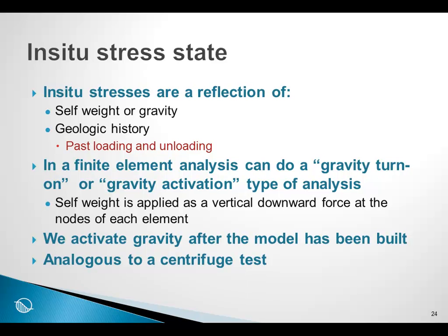In a finite element analysis, we can do what is called a gravity turn-on or a gravity activation type of analysis. And in this type of analysis, in essence, the self-weight of each element is converted into downward vertical forces at the nodes of each element. Now, it is rather curious that in real life, of course, gravity always acts, but in a finite element model, we activate the gravity after the model has been built.